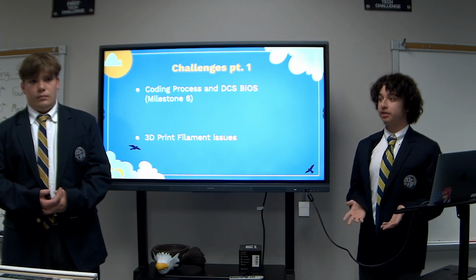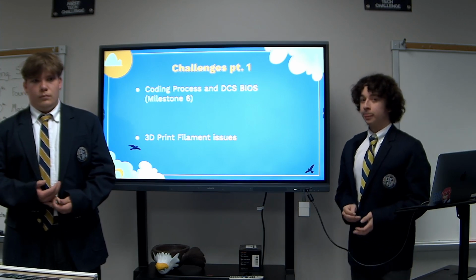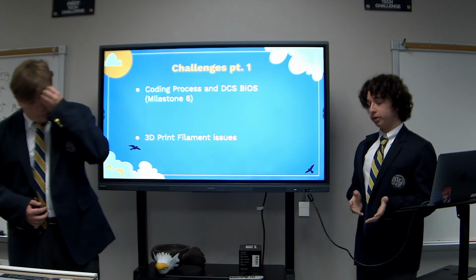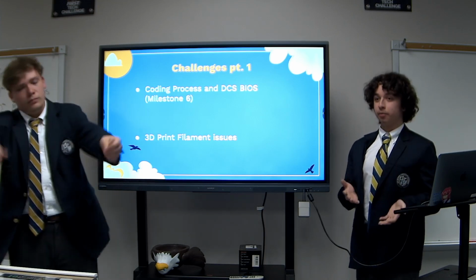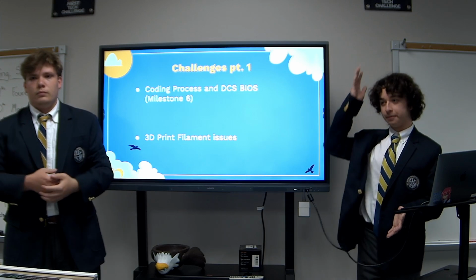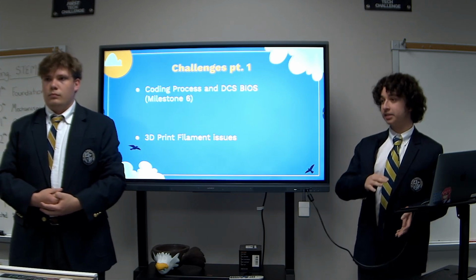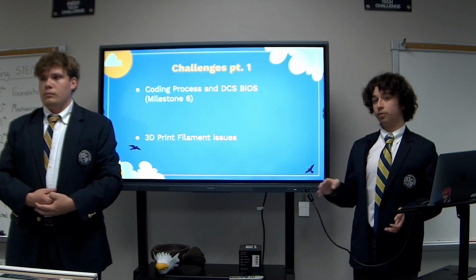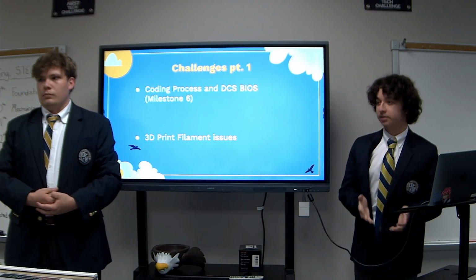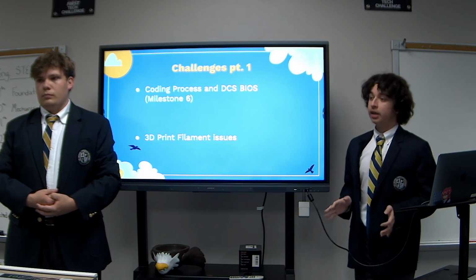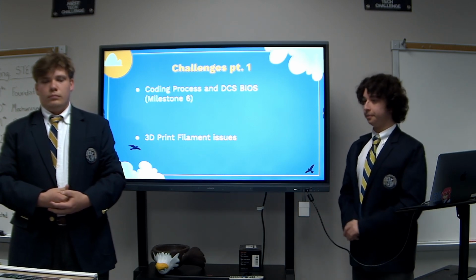Printing orientation is also another big factor that I found out is really important. If, for example, we print something vertically, it will have weaknesses in the layer lines. So then I would have to reorient the object to print it horizontally so that it wouldn't break as easily.